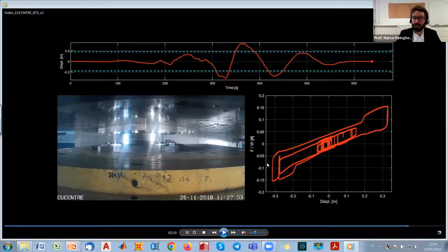Ordinary damage can be just very little detachments of the sliding materials, rather than some buckling effects of these sliding surfaces, because actually the sliding surface is made up of a backing plate, which is a spherical shape, and then a very thin layer of stainless steel. So maybe if the layer of stainless steel is too thin, you can have also buckling, but those are the main signs of damage which can occur.